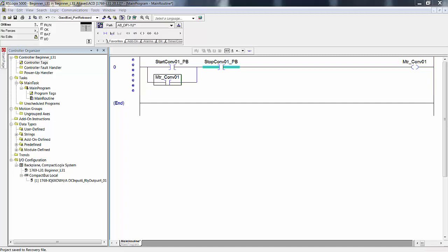So do yourself a favor, get used to using concurrent engineering, writing your programs without using the I/O assignment. If that is, it's not already done. If it's already done, well, then you're stuck with it somewhat. Either way, you're better off writing your program without assigning I/O and then go back and alias it to actual I/O. Either way, it's going to work out better for you.